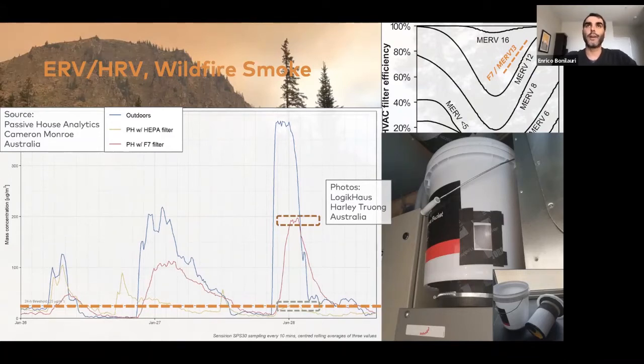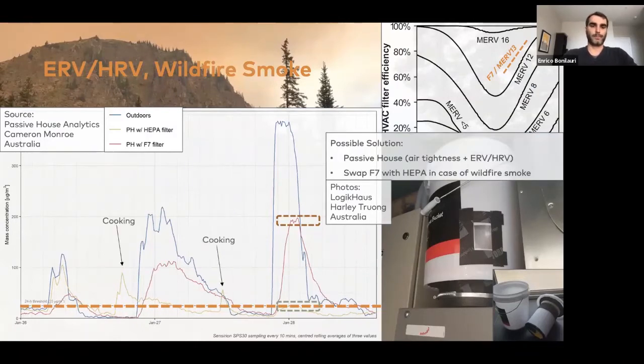So long story short, the combination of air tightness and mechanical ventilation does provide the building with better energy efficiency, but the main goal is to actually provide control over the indoor air quality. That is, air tightness keeps any pollution out, and then you filter whatever comes in.